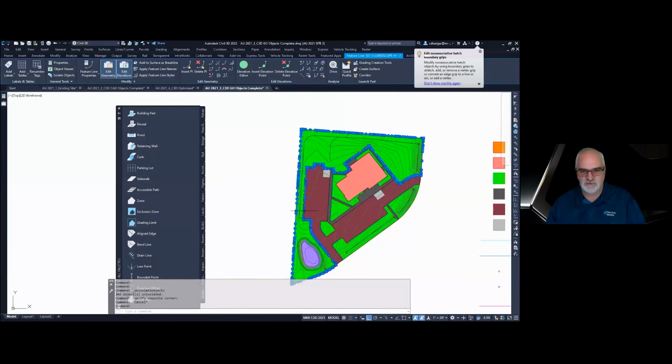So say this isn't what you wanted to do within the grading of the landscape, you can start with these feature lines and meld it to the way you want it to be and refine it more, or just modify the feature lines and add them to the surfaces and rebuild the surface with break lines and the points that it brought in. So it's getting you to a more complete point with your grading and helping you determine where to go from there.